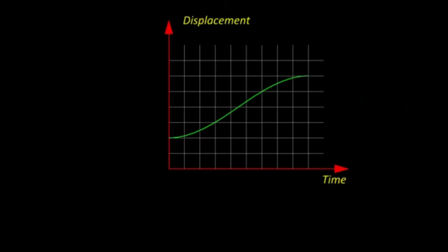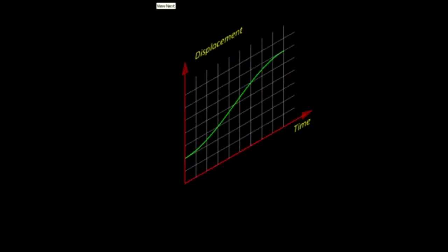The basic idea that we are going to use to solve this problem is very simple. Suppose we have been given a displacement against time graph, which is to be achieved so that a machine part moves according to this function against time. What we do is we take this graph, we cut it on a physical plate, maybe a thick metal plate.